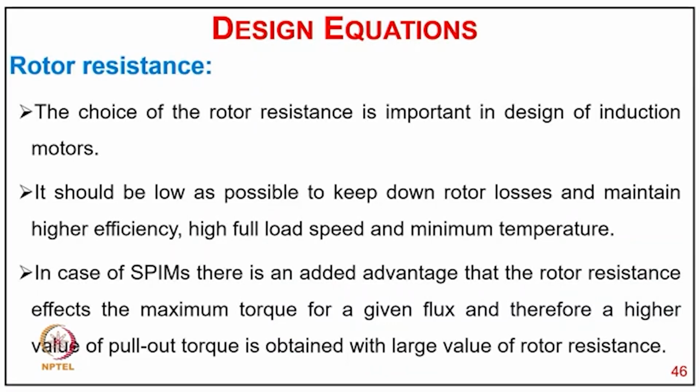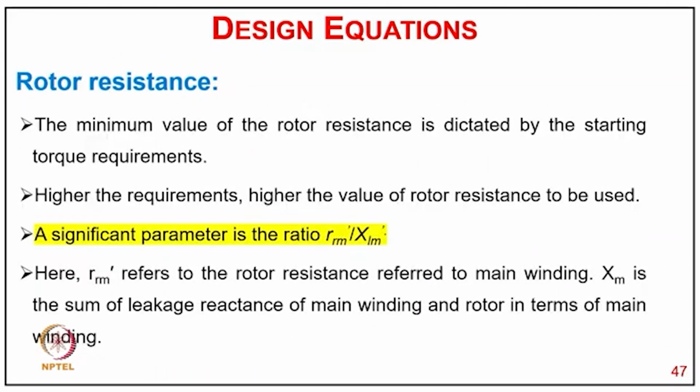So now coming to rotor resistance, the choice of rotor resistance is important in the design of an induction motor. It should be as low as possible to keep down the rotor losses and maintain higher efficiency, high full load speed and minimum temperature. In the case of a single phase induction motor, there is an added advantage that the rotor resistance affects the maximum torque for a given flux, and therefore a higher value of pull out torque is obtained with a large value of rotor resistance. The minimum value of rotor resistance is dictated by the starting torque requirement, and the higher the requirement, the higher the value of rotor resistance to be used.